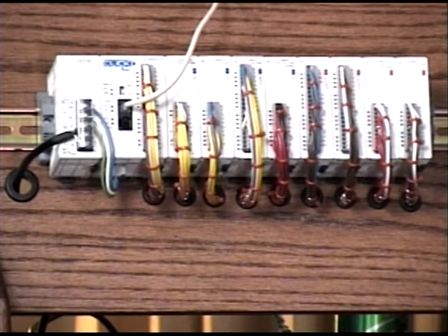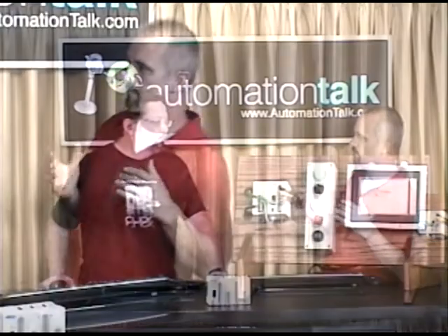Now, Richard, if you get up to 8 I/O modules, that's pretty much it. There's no expansion. There's no remote I/O or anything like that, right? No, not really. I mean, you could possibly communicate to another CLICK rack over Modbus or something like that, but there's no true remote I/O for this. I mean, 8 modules is about it. It's designed to be a small PLC where you're using it for a small application, where you don't have a whole lot of I/O. If you need more I/O, you might want to look at a DL06 or a 205 PLC, or maybe even a Productivity Pro. Right. That's why we did that. We try to bring it in as a low cost, get you in the door with the cheapest PLC that we could get you in there with, free software and so forth.